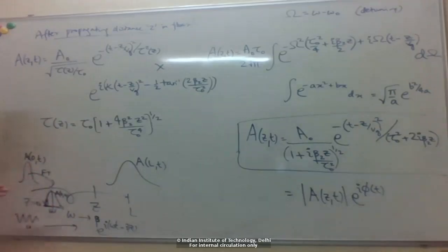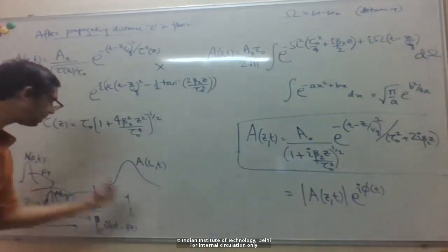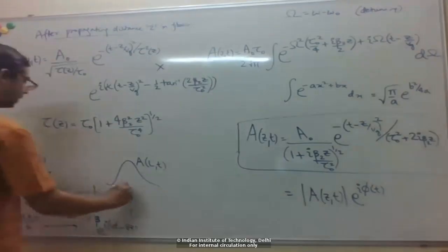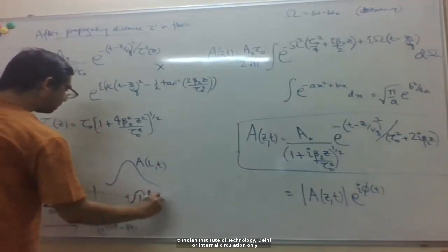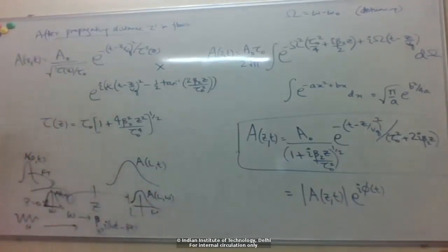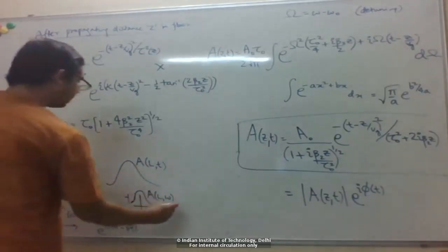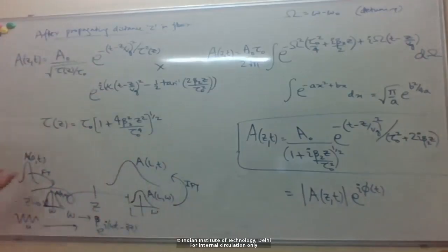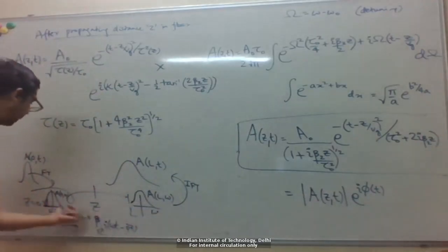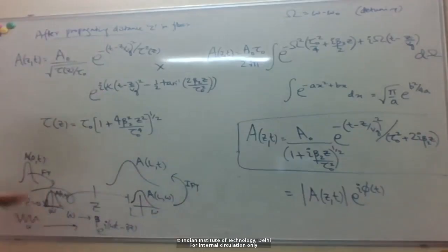Now we know each frequency just travels through the fiber like a phase, so for each frequency component we multiply by this phase, and we easily get the spectrum at the output. Then to get the time domain, we just take another inverse Fourier transform. That's why we're taking Fourier transforms: we know what happens in the spectral domain, and we can do it mathematically very easily because it's just a phase. So you first go to the spectral domain, calculate the propagation, and go back to time.